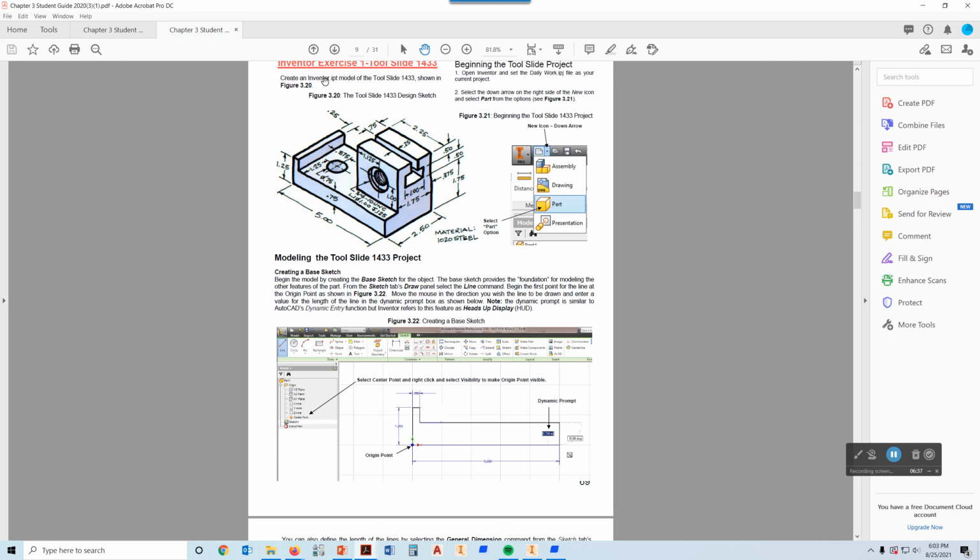When I look at that, I look at this base right down here that's 5 inches long and 0.75 tall right here, and it's 0.125 tall along this axis, and it's 0.25 wide. And so what I would do is draw that profile right there, and we call that the base sketch. That's what I would choose for my base sketch.